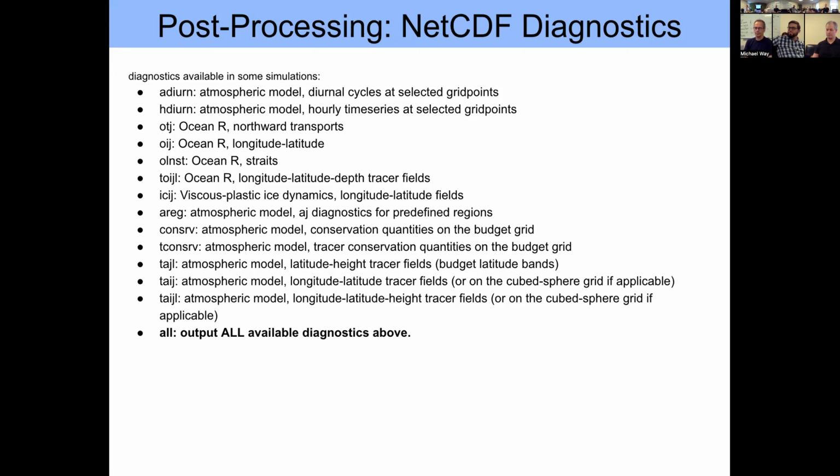So the important thing is that when you run the scaleacc program, you essentially type scaleacc, then the ACC file name, and then you need to type which of those files you want in the output. So if you want the AIJ file, you say scaleacc, space, the ACC file, space, AIJ, and that's it. If you want multiple, you comma separate them with no spaces: aij, comma, aijl, comma, etc. And if you want really everything, instead of naming them all, you just say all, and that's it.